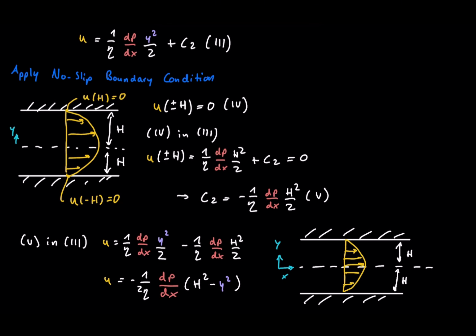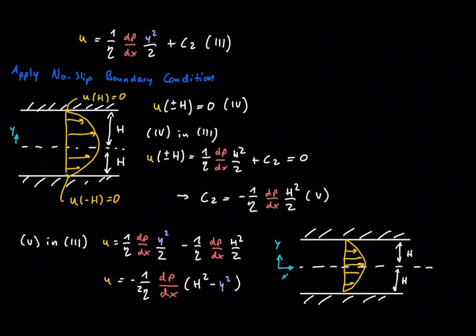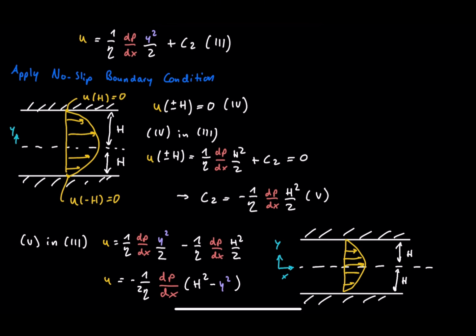Pause here and reflect. The solution strategy matters more than the formula. Control volume, force balance, constitutive law, boundary conditions. Geometry only enters through those boundary conditions. Once you master this workflow, you can solve variations effortlessly: one moving plate instead of two fixed ones, one plate only, inclined plates with gravity included, different fluid models, same steps, same logic, same confidence.